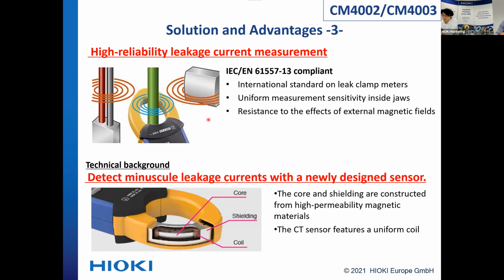The noise means busbar currents generate a large magnetic field, making it difficult to measure small leakage current in those noise environments. This noise is nearby because the wires are normally crowded in the distribution panels.